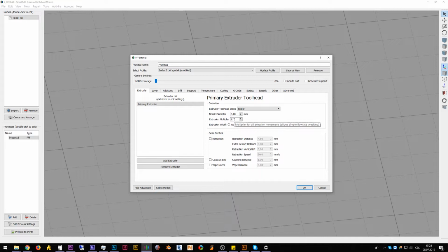This is really easy, no rocket science. The second number, the smart extrusion, is a little bit of rocket science. This number means the thickness of your extrusion which will be used for drawing the graphic. And if, for example, your graphic is too tiny for this thickness, this graphic will be ignored.